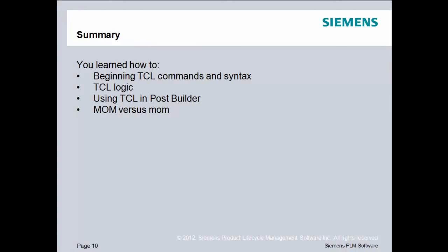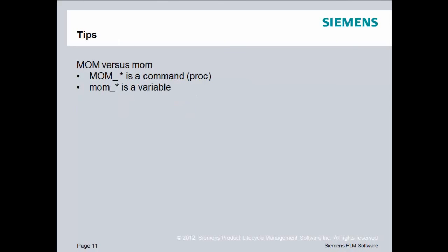To summarize, you learned how to create beginning TCL commands and syntax. We talked a little bit about TCL logic and how it works. We also used TCL in PostBuilder with some of the PostBuilder specific commands like mom_output_literal. Finally, we talked about uppercase MOM versus lowercase mom. As a reminder, uppercase MOM is a command or proc. Lowercase mom indicates that that is a variable.